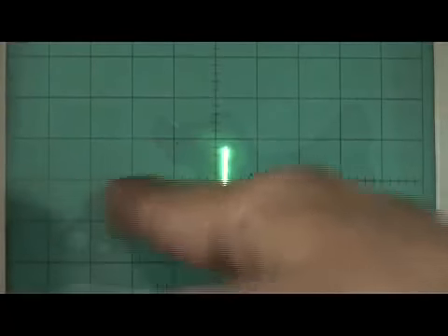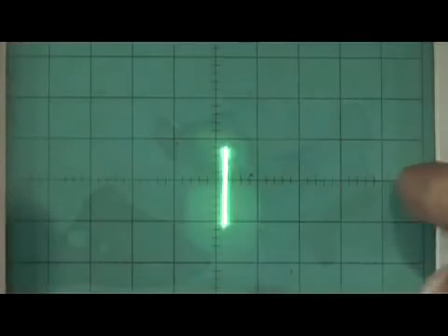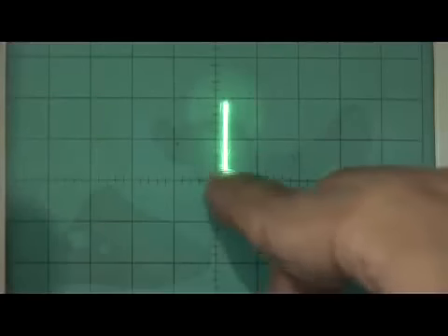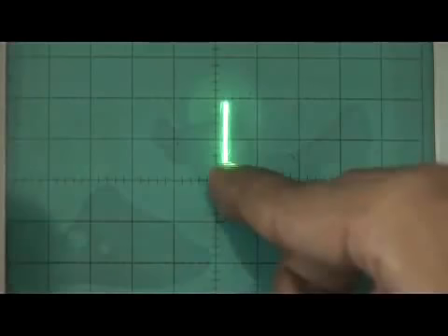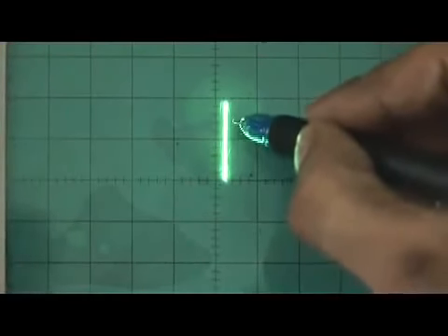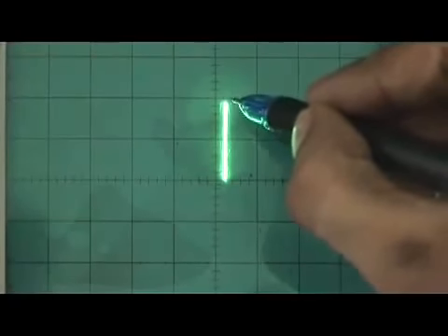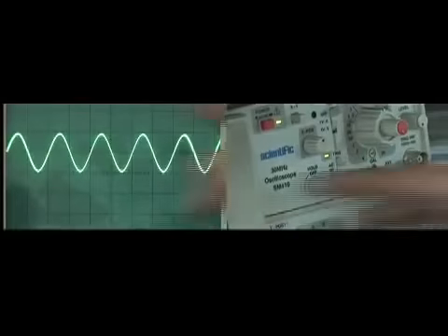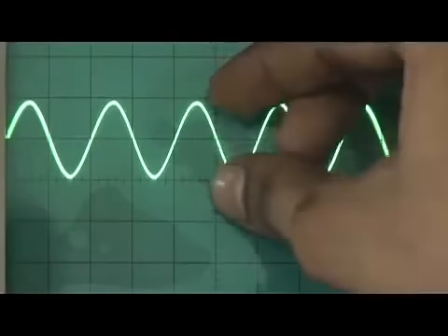Now, this dark black line, which has subdivisions, is your reference line. Using this Y position knob you can move this line and bring it over here so that you can properly count the number of divisions. Now it is here. From here, if I count, it is complete till here, 1. From here it is 1.2, 1.4, 1.6, 1.8. It is almost touching 2 but not 2, so let us take it as 1.9. I release the XY. So it is 1.9 blocks that it is taking for this amplitude.